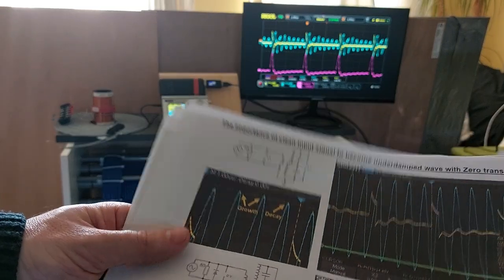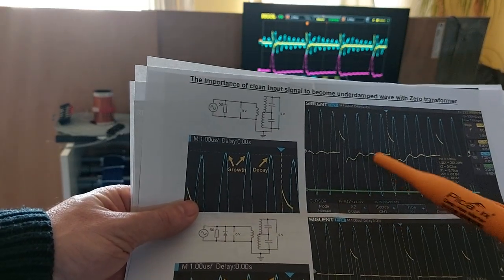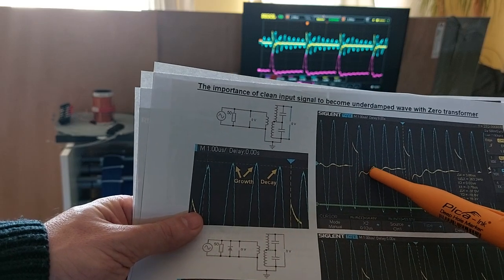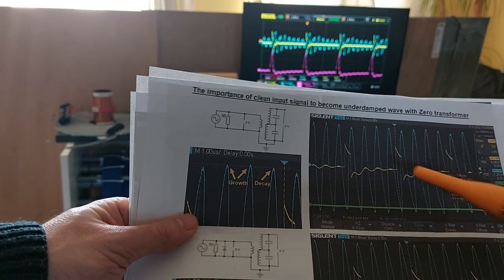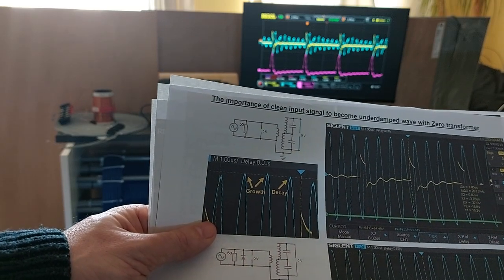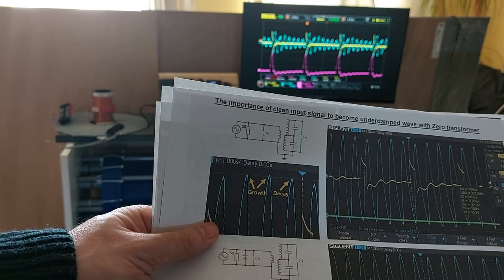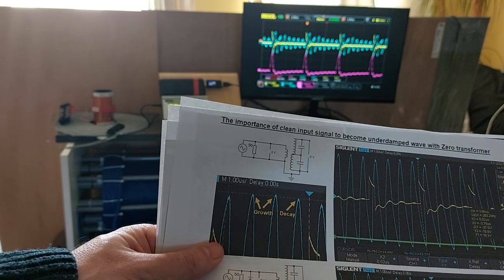As you can see in this circuit, also linked in the picture. So this is without the diode, where we have that negative going signal and we have ringing on the input, and then where we have the diode across it, we have that clean input pulse, and you can see that the waves are better in those cases.